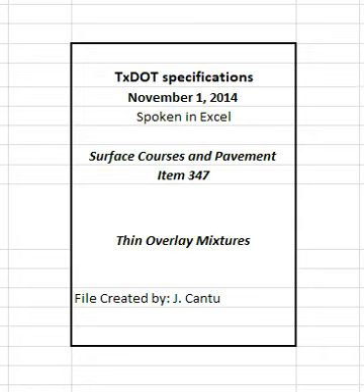Notify the engineer if electing to proceed without Hamburg wheel test and overlay test results from the trial batch. Note that the engineer may require up to the entire sublot of any mixture failing the Hamburg wheel test or overlay test to be removed and replaced at the contractor's expense. 4.4.2.1.16 Development of JMF3. Evaluate the test results from Lot 1, determine the optimum mixture proportions, and submit as JMF3 for use in Lot 2.